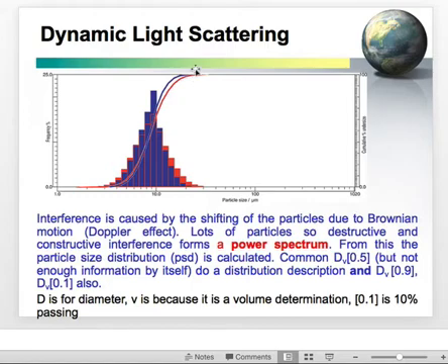If we look at here, this is the S type of curve. This is the cumulative percent passing, and so I can see the largest particle size here at 100% is here. So about 100% passes through about 20 microns. We do look at the average, and here we look at the D50. This is the middle point, or 50% passing, and we can work out that that's going to be somewhere in the 9-8 micron area.